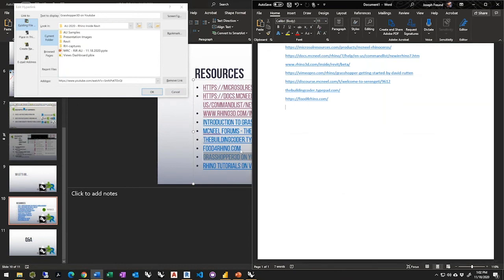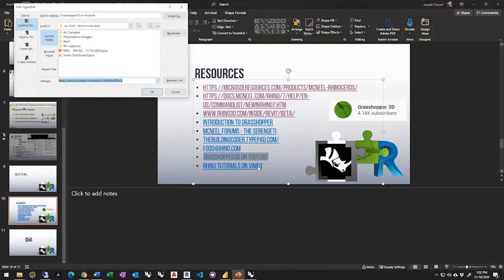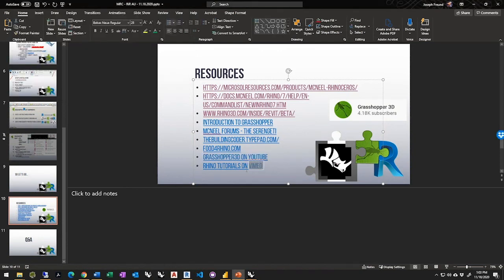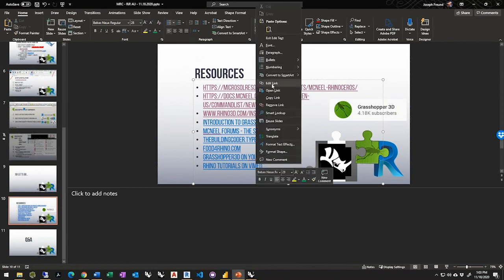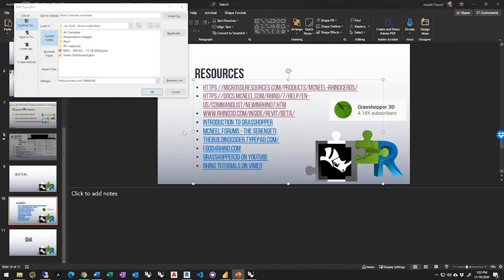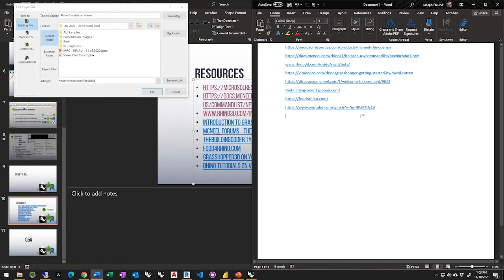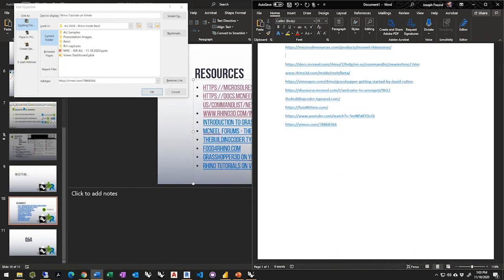So that's one. And then there's a lot of questions between direct shapes and elements. A lot of people are wondering about the extensibility of the editing capabilities in Revit, which Scott already answered. But just to reiterate, direct shapes are generic containers that can hold any type of geometry. Revit doesn't need to understand how that geometry is being generated. It's not generated from any metadata. It just gives you a container that you can throw stuff in.